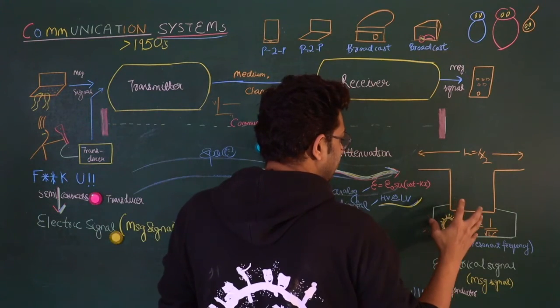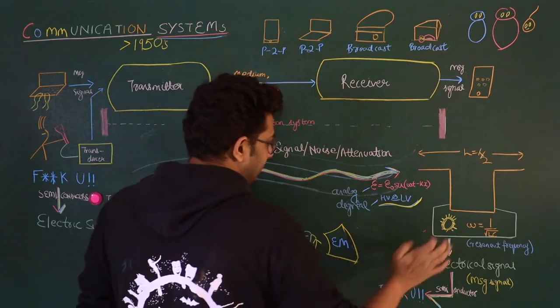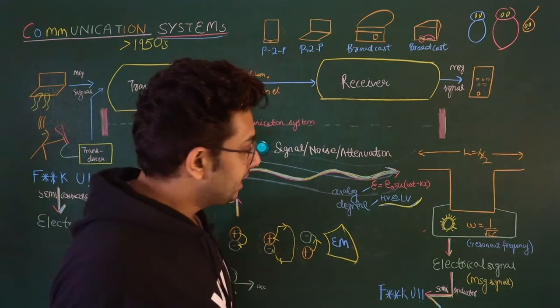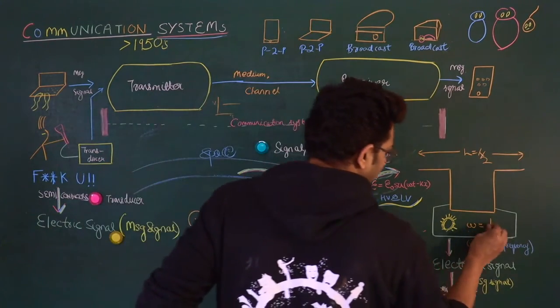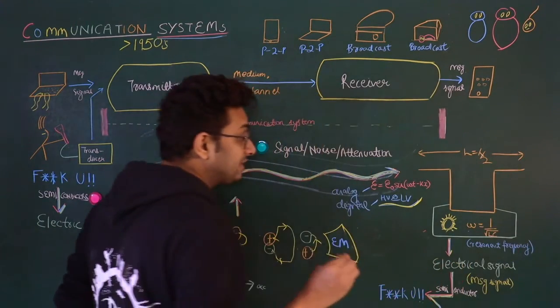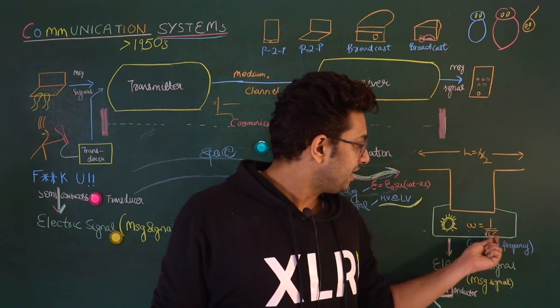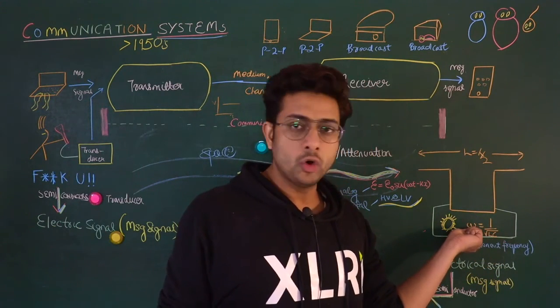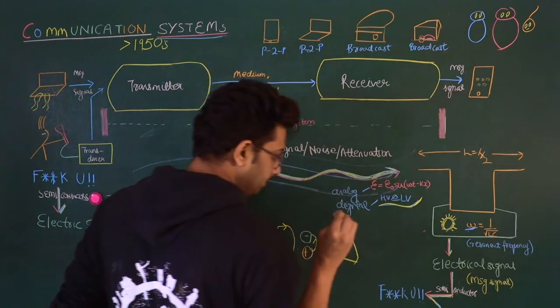What happens here is there's an antenna. Now this antenna has an LC circuit, right? LCR circuit, and the omega, if you remember, is given by 1 upon root LC, and this is the omega for resonance to occur. Now if I change my C, I can change omega, right? So this omega is in control.